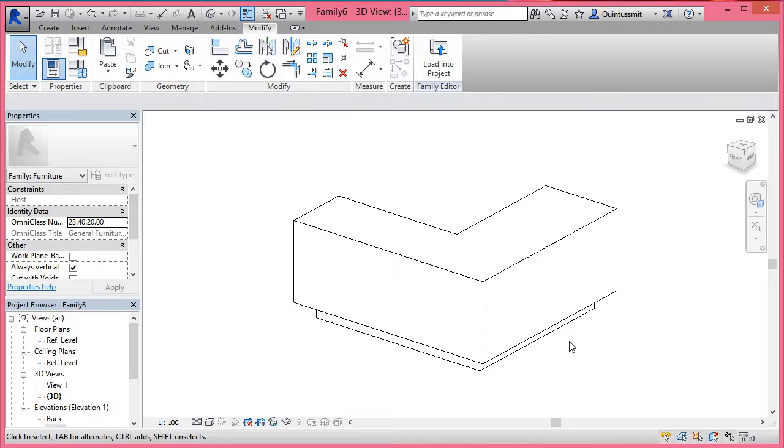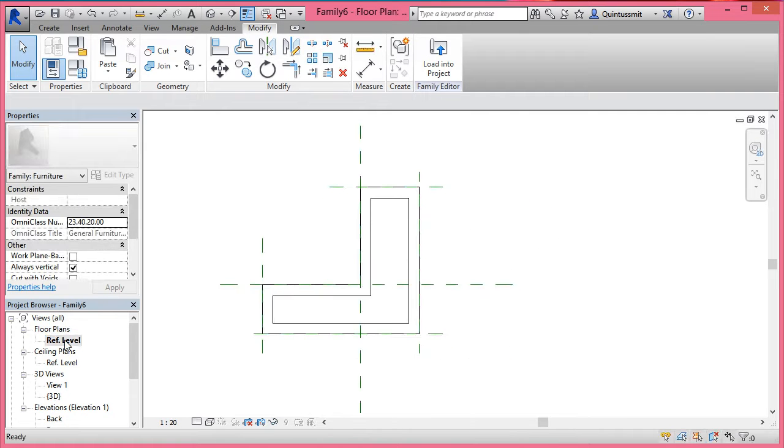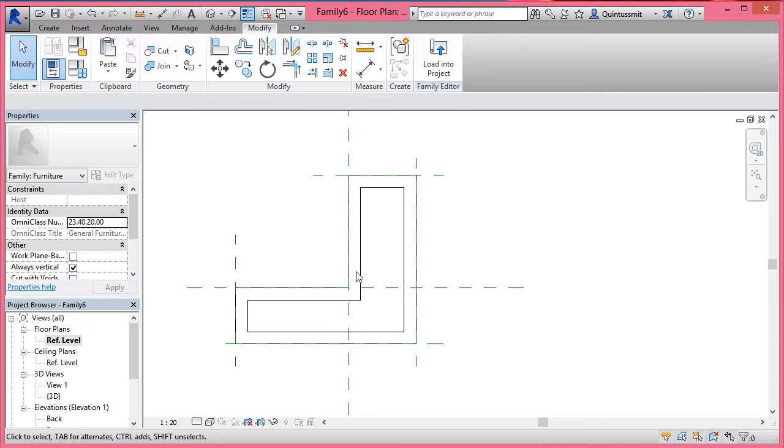Okay, now let's start carving away to make this more interesting. And I'm going to use a void for that. From experience, I can tell you that Revit works best as a subtractive modeling application, meaning it's easier to start with a solid shape and then start subtracting from it what you don't need than to build using basic solid shapes. It's also easier to add parameters to voids than to try and add parameters to solid elements that you've built in pieces.